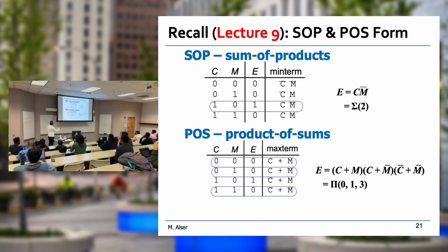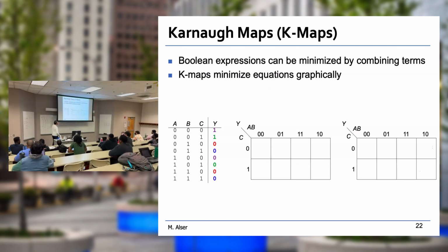And then whenever we have a 0, there is a NOT. Whenever we have a 0 over here, NOT over there. As simple as that. Now product of sums is the opposite. When we have ones, we should have a NOT. So 1, 1, NOT, 1, 0, NOT, nothing. When we have a 1, NOT. When we don't have a 1, then nothing. As simple as that. Do you understand this? Hopefully, no confusion so far. All right, let's move to the Karnaugh map.